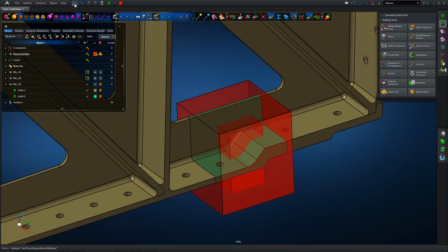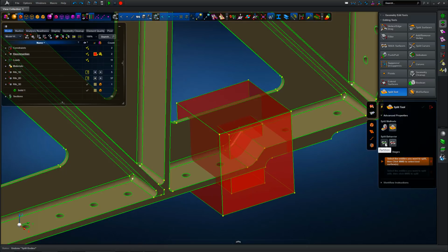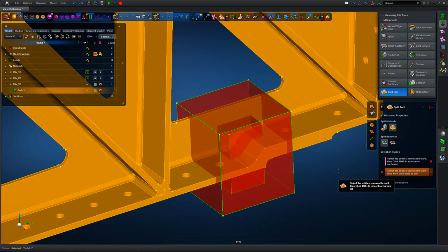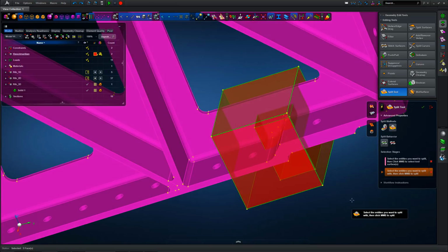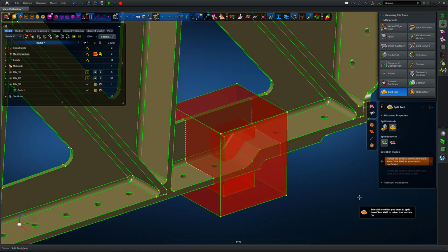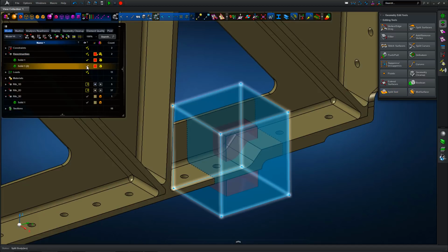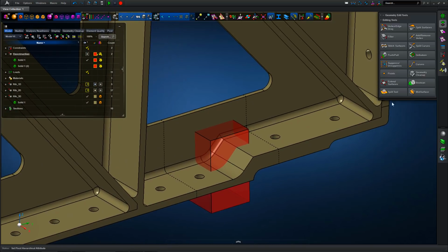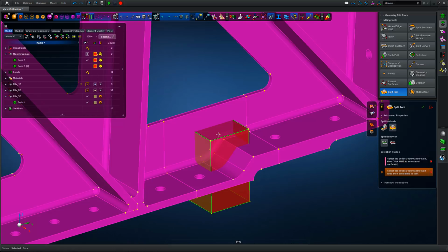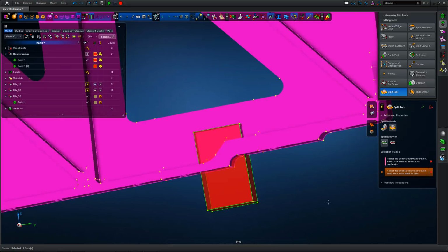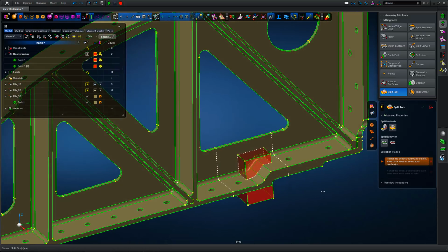If we were to mesh based on that definition, there would be no mesh congruency or nodal equivalence at those solid interfaces. So we're going to redo that process, but this time we're going to partition the solid about those faces, which breaks the solid down into, again, discrete regions or partitions, but in the model browser tree we can still see a single solid under the 3D rib definition. This gives us the ability to locally control the mesh density in a given partitioned region without having to use that mesh density everywhere within the rest of the model.